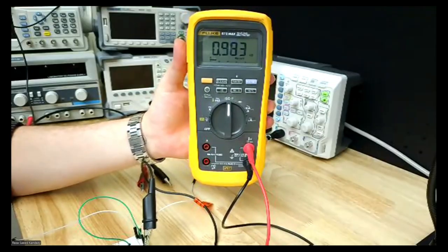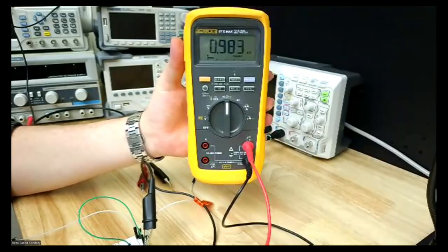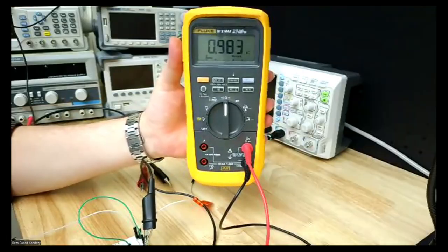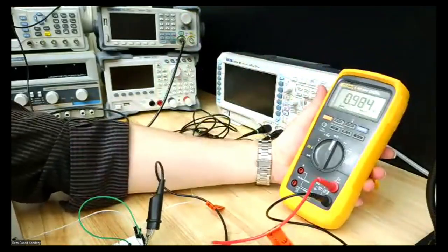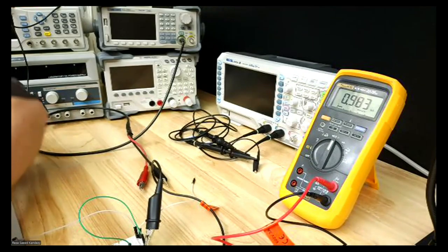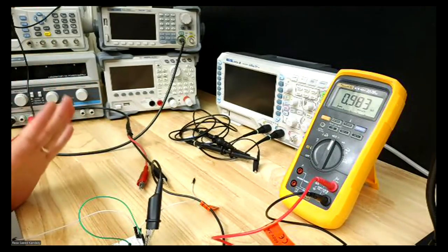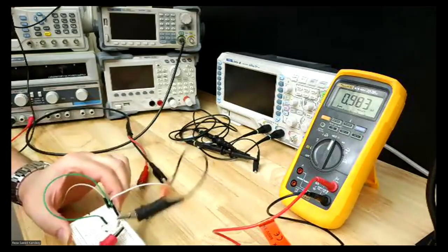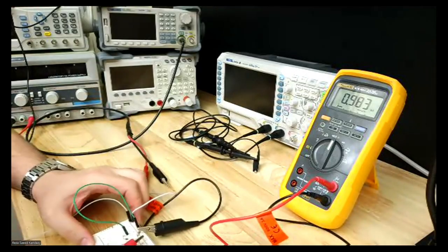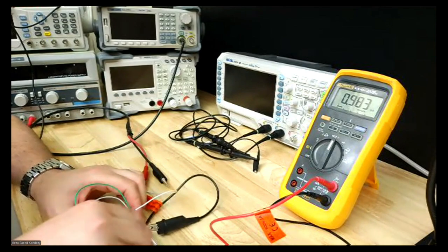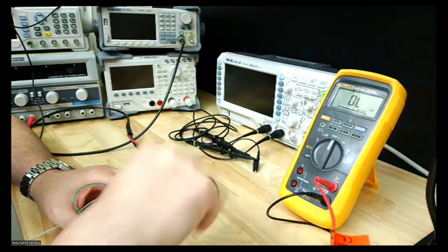So it's good that I've been conservative and chose the 1 kilo ohm, because even though there is a tolerance, I'm still above that safe resistance. Now, one thing to always remember when you want to measure the resistance, there should be no source connected to your circuit. So the circuit is de-energized. Otherwise, it would affect your measurement.